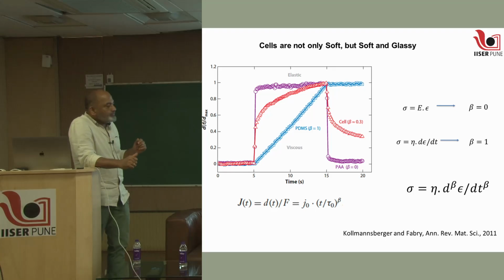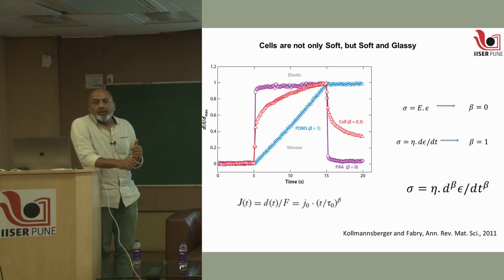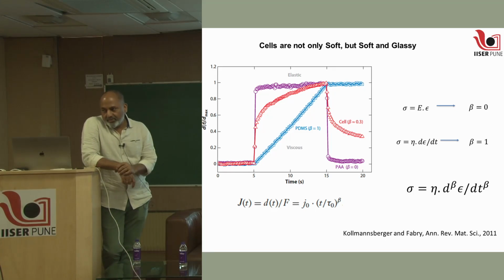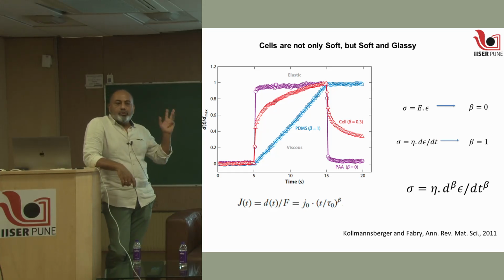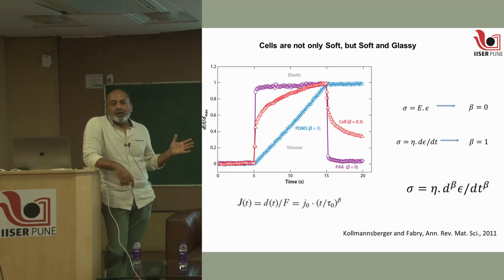So these are solids. Then we have something called Newtonian liquids, and Newtonian is important here. Just as these solids are also called Hookean solids because they follow Hooke's law, we also call them Newtonian liquids, which means they follow Newton's constitutive equation. It is not the standard Newton's law of motion or gravity. This is a specific equation that Newton came up with that describes the response of liquids to external forces.